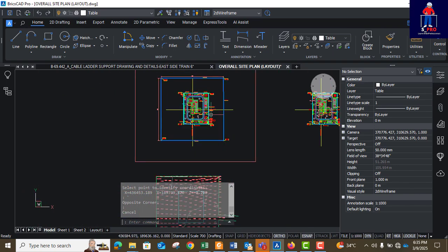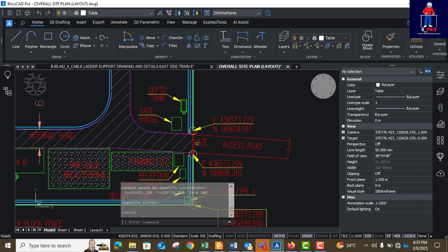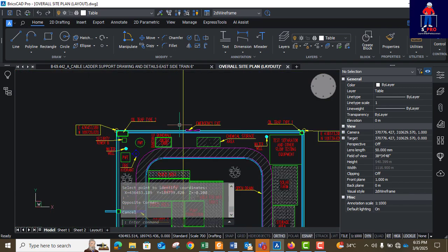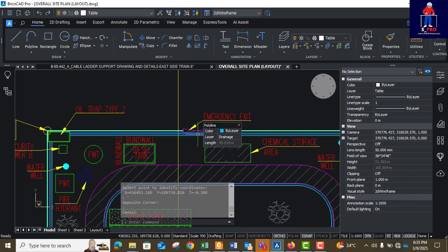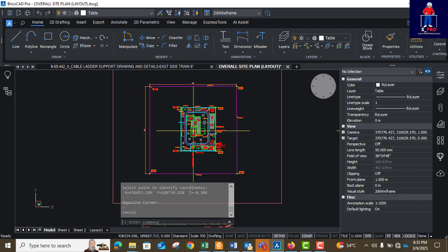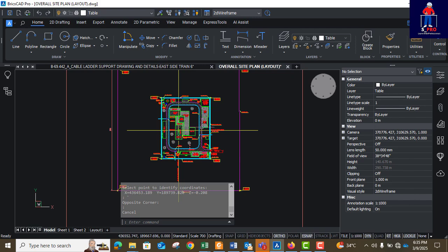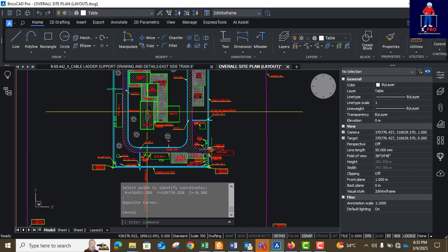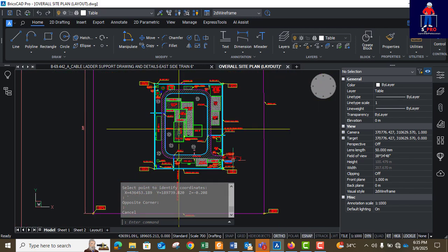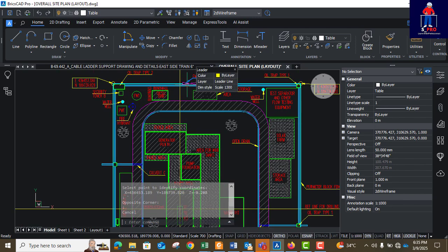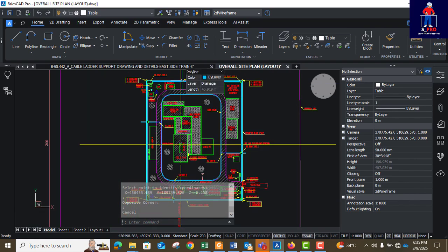Everybody that is coming to this plant will come from the access. Everybody comes and leaves from this access, but there must still be an exit gate. It is standard in oil and gas, so you must have an exit gate. This is in case there is any fire outbreak, somebody who is here shouldn't have to come all the way back before they can escape the facility. You can follow whichever one is closer to you at that point to escape. Okay, that one is for gates.